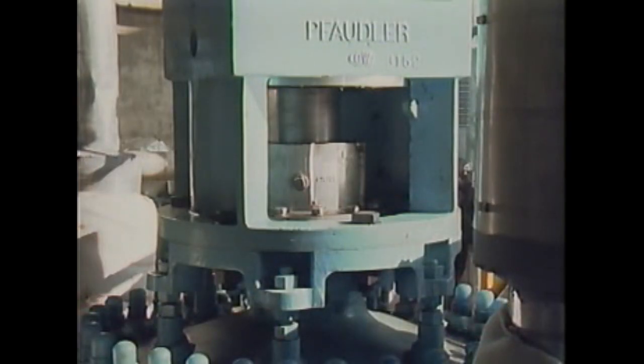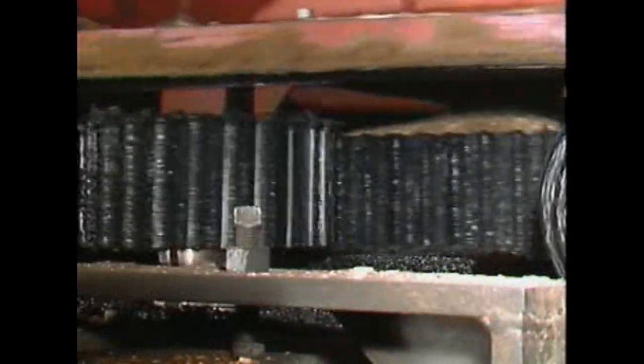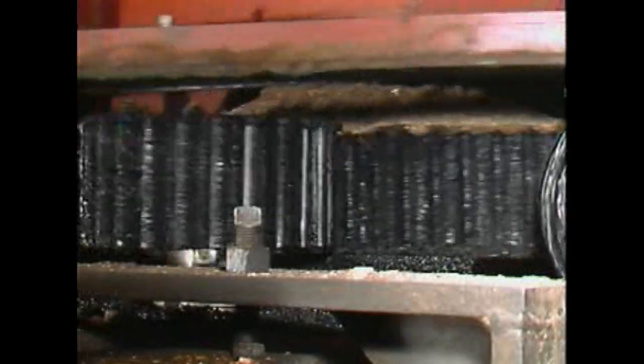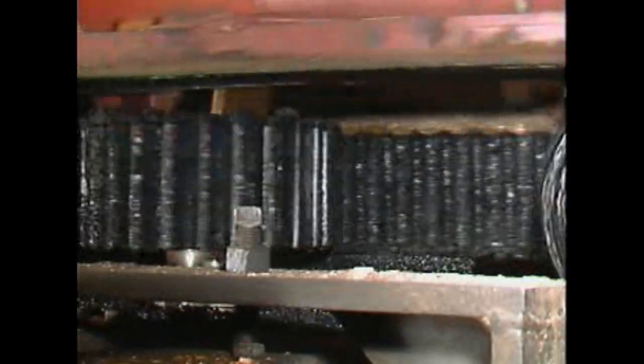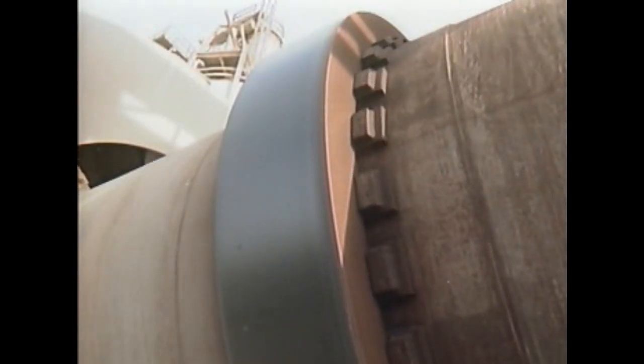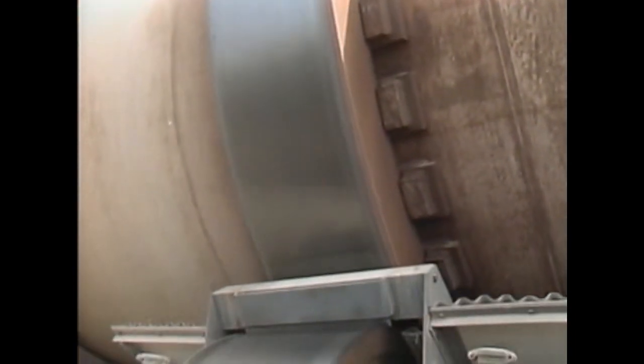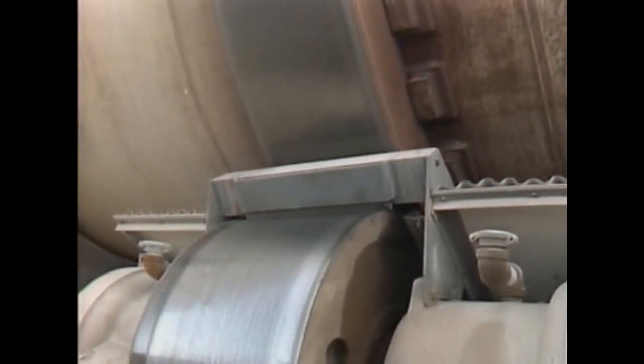Various factors determine the appropriate lubricant for a given situation. For instance, pressure or load affects the selection of a lubricant. An application with relatively high pressure requires a lubricant that won't flow away from where it's needed when the pressure increases, such as when gear teeth mesh. Applications that involve relatively high loads or pressures typically require greases, solid lubricants, or high viscosity oils.